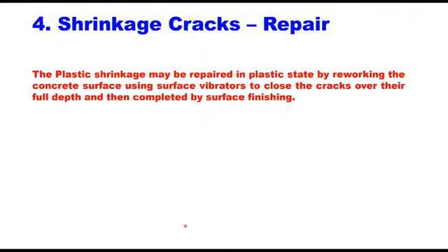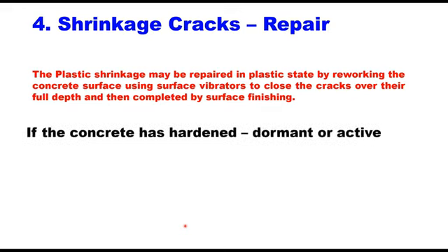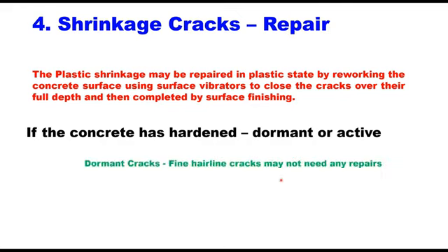If the concrete is in plastic state, then plastic shrinkage cracks can be repaired by reworking the concrete surface using a surface vibrator and closing the cracks to their full depth and then completing the surface finishing. But if the concrete has hardened, then the cracks may be either dormant or active. The dormant cracks do not move with time, or they do not open with time.